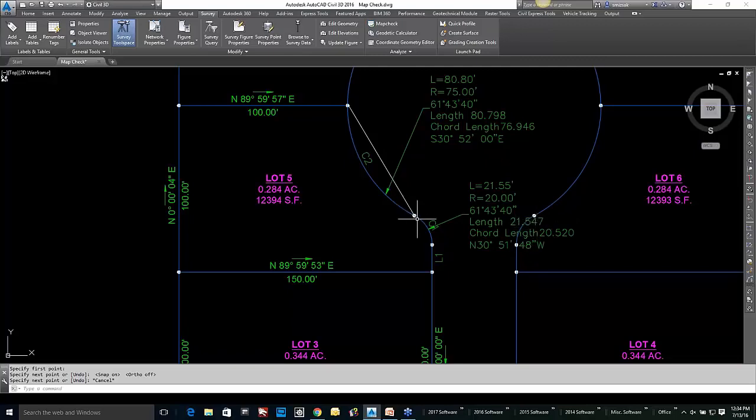And then a 20-foot radius would have actually put it as a curve to the southwest. I had to put in a negative radius of 20 feet to get it through here. And then the L1 line was just 16.33 feet southeasterly 1 second. And then I came back through northeasterly 89, 59, 53 to close it out. So that was a verbal demo of what I did.